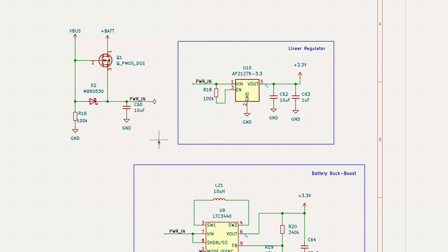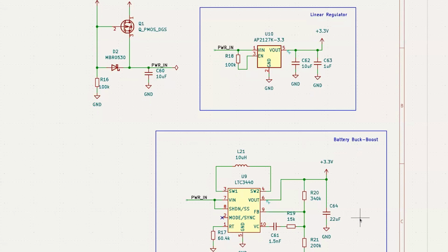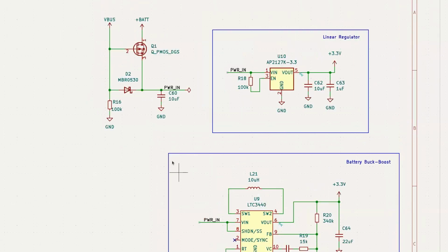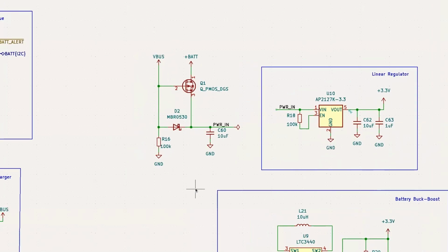Or if we want a battery source that may not make it up to full power, if we're using some type of energy harvesting, there's a number of reasons you would want to use a chip like this. Exactly right. If you're using a supercap, it's going to drain all the way down to 0 volts, and all of that is usable energy. You're only going to be able to make use of that with a buck boost. So for $5, in certain cases, yes, it's definitely worth it.